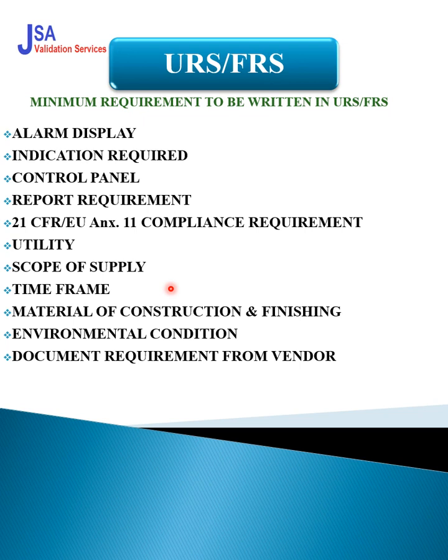Then environmental condition, where you are going to install your compressed air system, that is very important. If you design your compressed air system at a humidity of 40% or 30% in that area, and suppose you are going to install your compressed air system in a tropical area where the humidity is 80 to 90%, then there is a huge difference in the design. So environmental condition, temperature and humidity, should be mentioned in the URS. What is your environmental condition at the service floor or where you are going to install that air compressor.